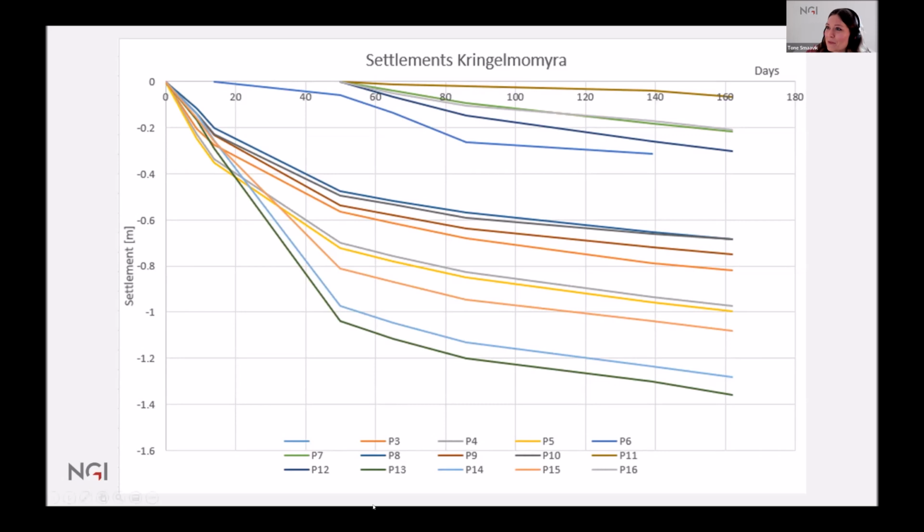Yes, we are. One thing to say about this slide is that the graphs, the curves starting from 0, start measuring after the first 1.5 meter fill is put in place, because that's when you have the largest movement. So we're not counting those. There is an element of not just normal settlements, but larger movements in the peat when you place that first fill.